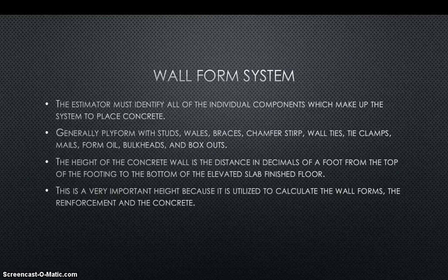The height of the concrete wall is the distance in decimals of a foot from the top of the footing to the bottom of the elevated slab finished floor. This is a very important height because it is utilized to calculate the wall forms, the reinforcement, and the concrete.